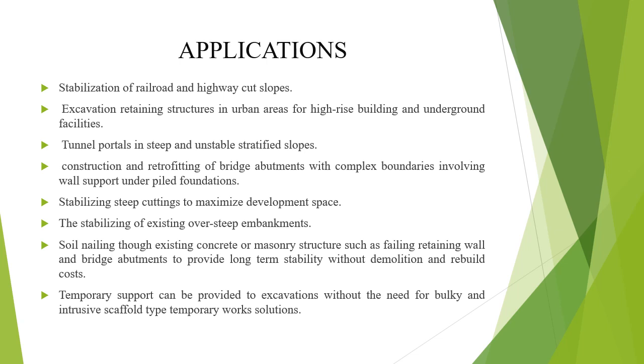Soil nailing through existing concrete or masonry structures such as failing retaining walls and bridge abutments to provide long-term stability without demolishing and rebuilding cost. Temporary support can be provided to excavations without the need for bulky and intrusive scaffold type temporary work solutions.